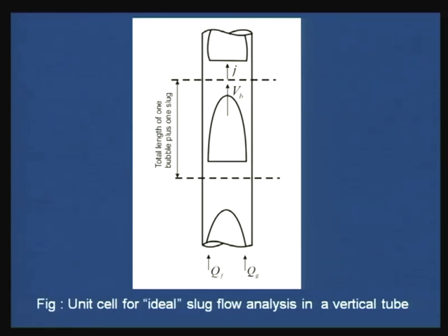But the moment it reaches the intersection of the nose and tail region, this nose region is quite small. After that, it attains a terminal film thickness and flows down at a constant velocity. When it is flowing down at a constant velocity, that means the wall shear completely balances the weight of the liquid. Yes or no? It must completely balance the weight of the liquid, due to which the liquid becomes a free falling film under this condition.